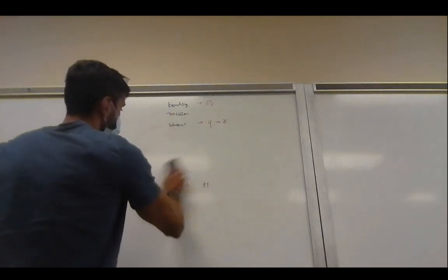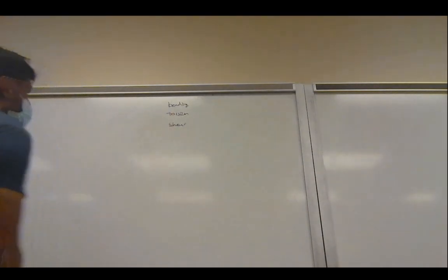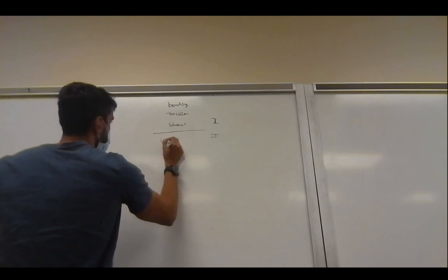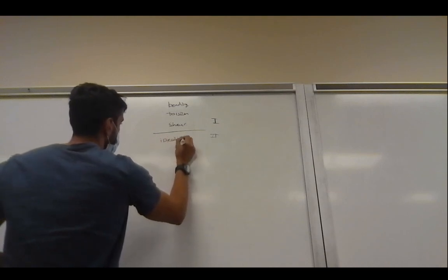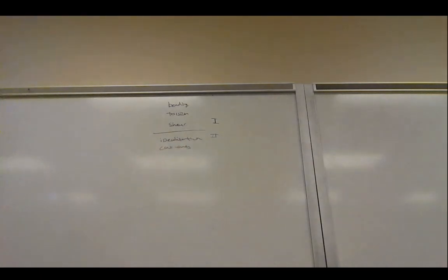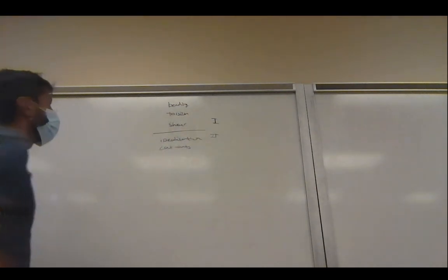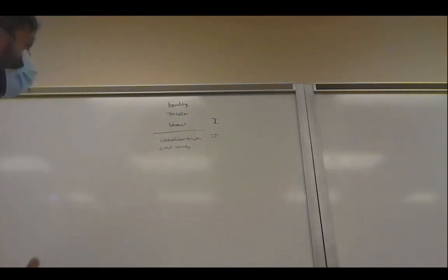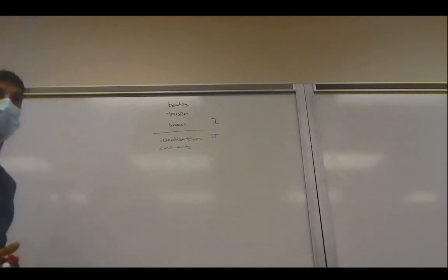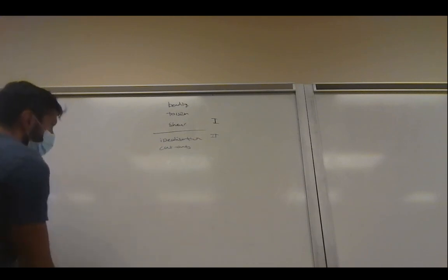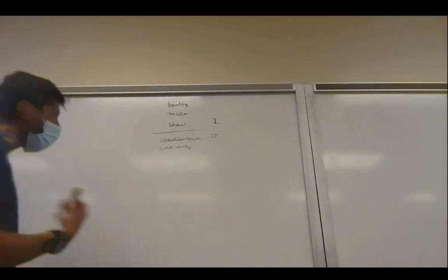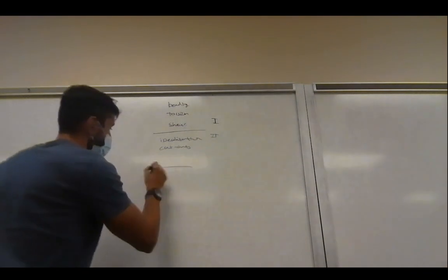That was basically the first part of our lectures, and the later part we went to idealization and cutouts in this case. So basically idealization is a method to simplify our bending shear flow equation that we saw earlier. It doesn't change anything, it just makes our lives a bit easier in the analysis step. For cutouts, on the other hand, we have to be a bit more careful. So basically we have to calculate the effect of a missing panel.